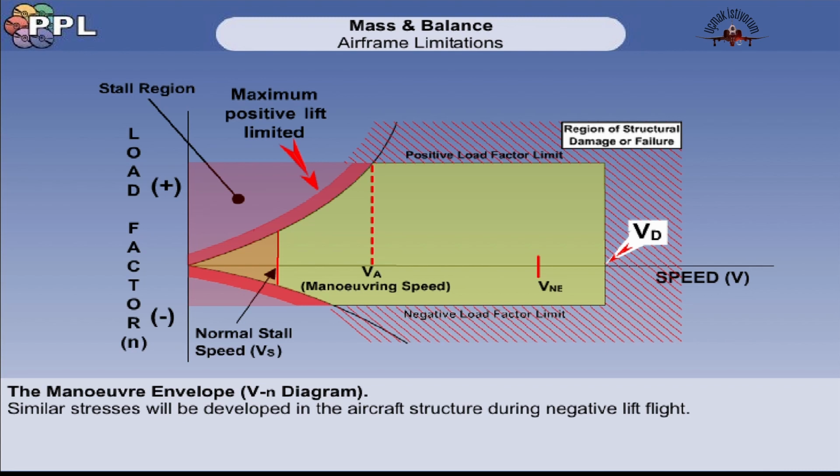Similar stresses will be developed in the aircraft structure during negative lift flight. However, the negative load factor limits are set lower than those for positive lift flight. We now superimpose upon the manoeuvre envelope the significant speeds and speed ranges with which, as a pilot, you will have to be very familiar.